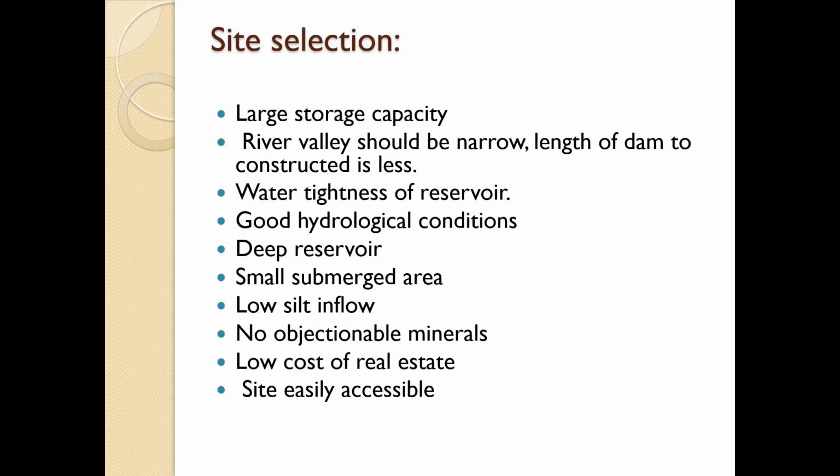Then a small submerged area should be there, because if the submerged area is more, then obviously there will be the problem of relocation of the people, or whatever damage is done to the environment, which we also need to think about. Then obviously low silt inflow.